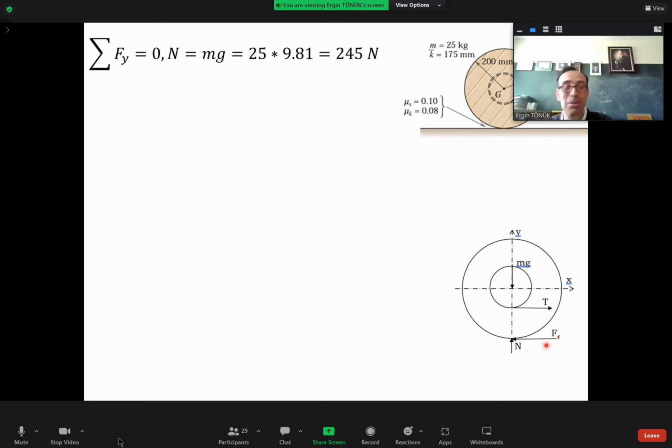Clockwise moment. Yeah, that would be tricky. Suppose T were here. So it's trying to move the mass center to the right. Friction force to the left is going to prevent it, but the moment of T about the mass center is clockwise, so it will try to rotate it clockwise. So a friction force trying to prevent that would be to the right.